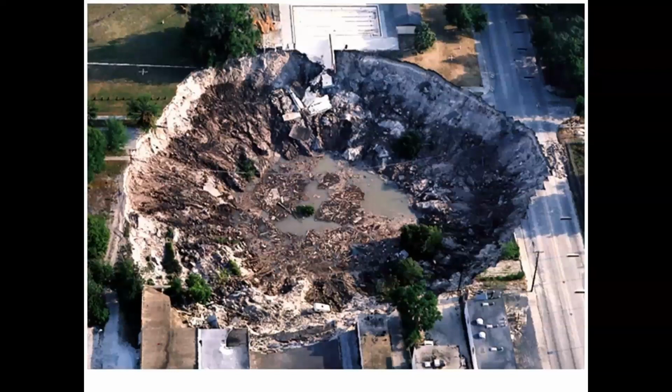Here's another picture of a sinkhole where you can see a similar thing has happened. And any of the buildings that were around here just collapse right into the sinkhole when it occurs. And they can occur fairly suddenly. We can guard against them by doing seismic tests to identify places where there are caves close to the surface, but it's not always a perfect solution.